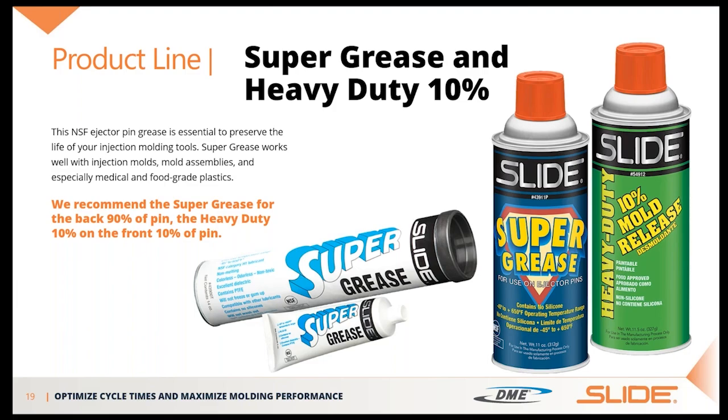So the super grease is an NSF certified PTFE based grease. It's opaque, so it's almost clear. It comes in aerosol form or the grease form. It withstands high temperatures also. So it's designed for ejector pins working all day, a lot of friction and a lot of heat.